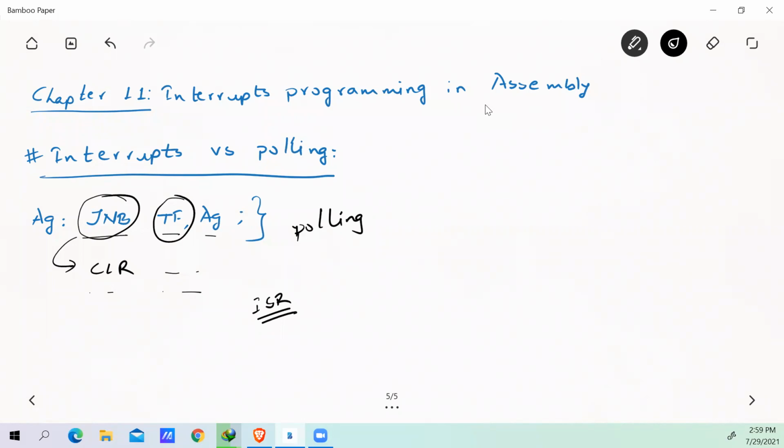Say your microcontroller is performing some task, okay? And then an interrupt has been invoked. Whatever your microcontroller was doing, it will finish that particular line of task. Then for the next instruction, your microcontroller will save the address in the stack, and it will save everything that has been done. Then according to the interrupt, your microcontroller will serve that particular device. After finishing serving that device, it will get back to whatever it was doing. Have you understood now? Yes, sir.